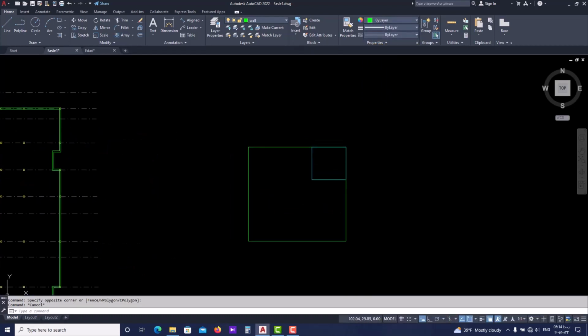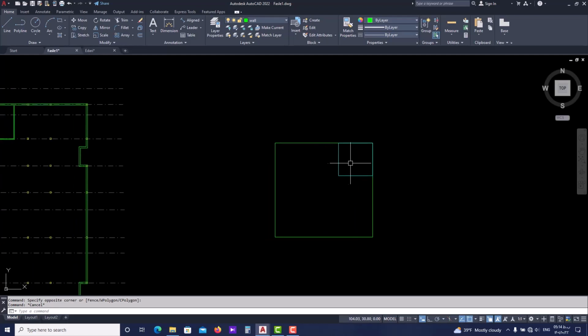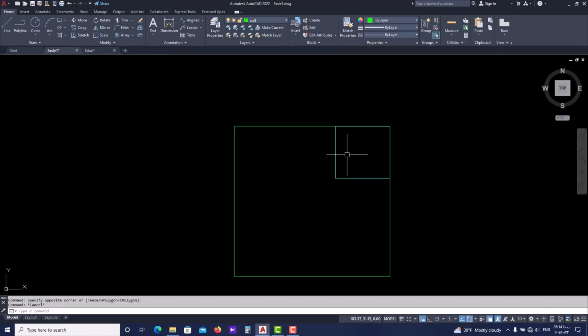So, guys, what I want to do here is I want to copy this rectangle here without using copy or move. So I can use another command called mirror. Mirror works as copy and move all together at the same time. And as always, we have some items and subcategory items that we can use in this command as well. All right, let's see how it works.